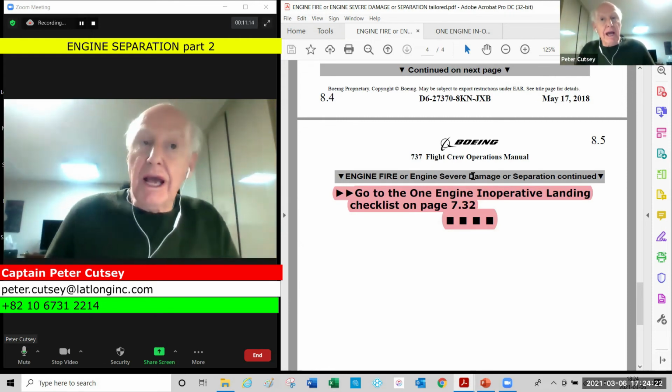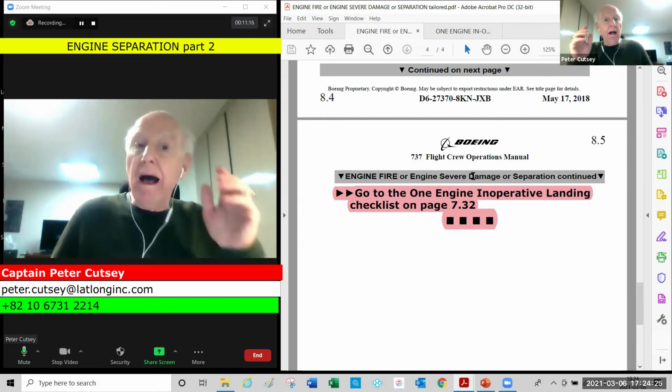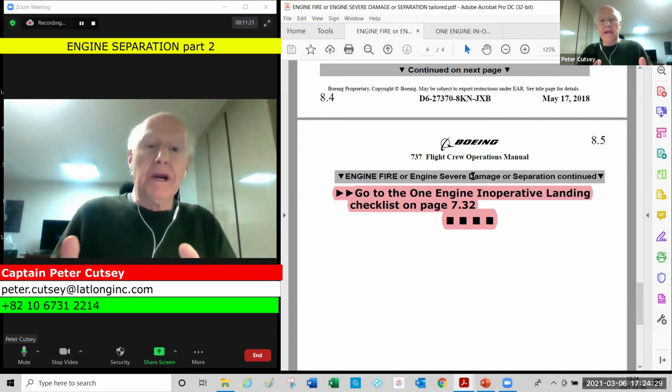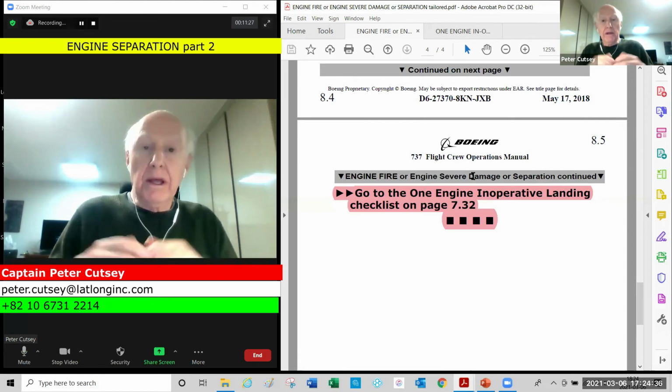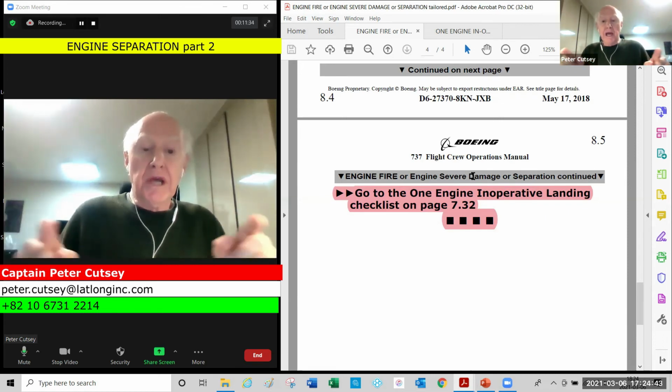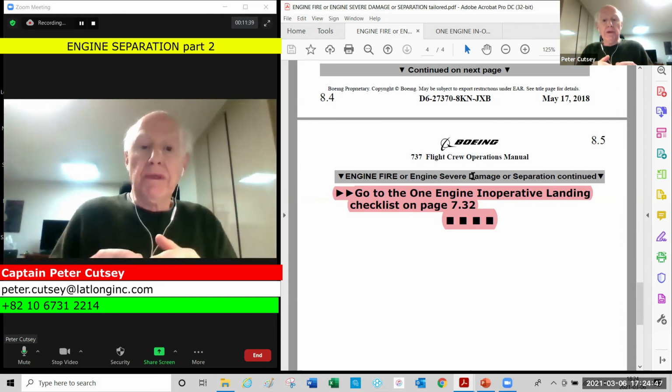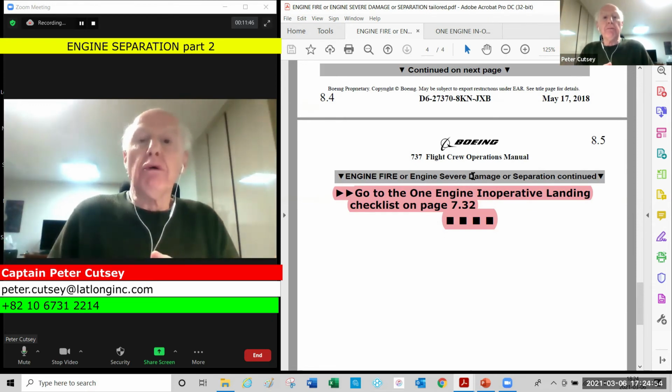Maybe you've got a checklist called fuel imbalance. Maybe you came down to the point where you didn't really think about balancing fuel before you got to the fuel imbalance. That's airmanship. And if you both agree that before you start doing any other checklist, and you both agree that you don't suspect a fuel leak, and you both agree that your company SOPs don't state that you can't do this by memory, get the fuel balancing done.